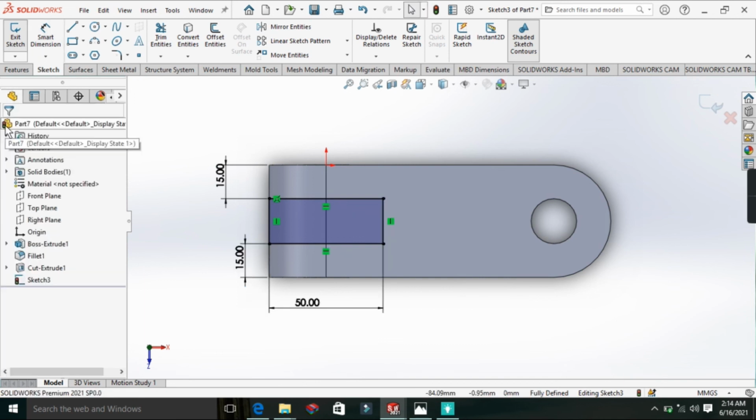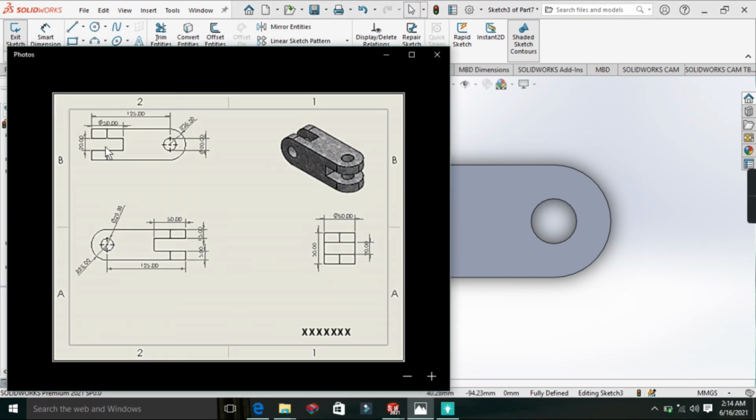So likewise the same thing for here too, it will be what, 50. So when you've done that, click on your check arrow. Done that. So the next thing you do, you go back to your diagram and check what you've missed. If you see you did not miss anything, the next thing is to extrude it, to create a space or a cavity or hollow at that place.